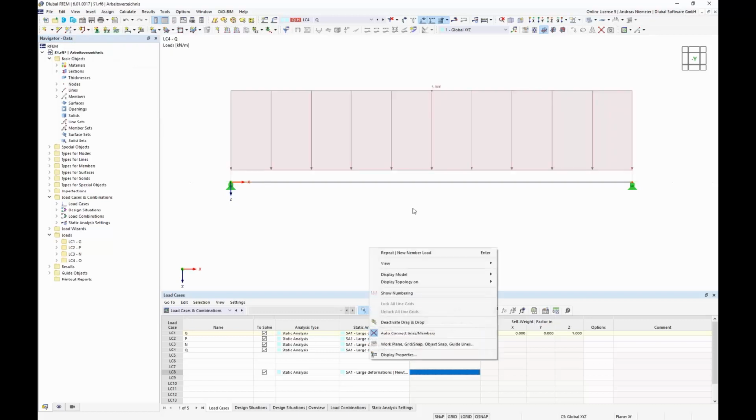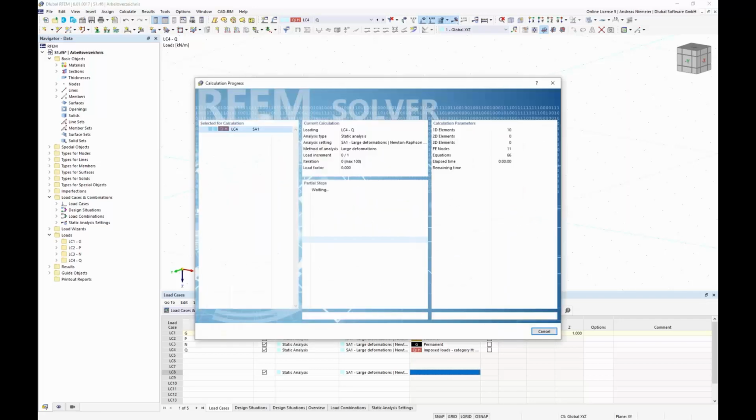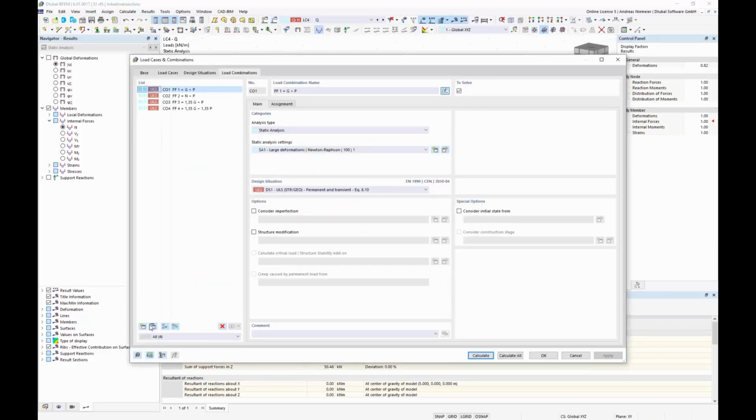So far we have a load on structure. If I run this load, what happens? Without any further specification, the program applies this load on the 10 meter long cable, yeah? And not in any shape. But if you want to apply it maybe on shape 1, you have to assign it. This means we go again into this dialog, load combinations, and say, please calculate, we give a name, Q on FF1. And this you can do if you define an initial condition or an initial state.